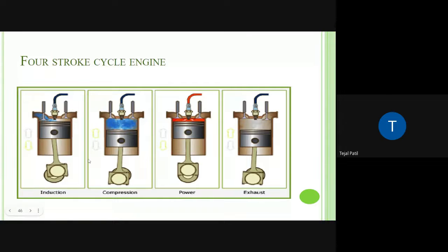So when it splashes, automatically that lubrication will be provided, that oil will be supplied to this moving part. Everywhere it will do splashing. That means the whole time the engine is going to be wet. That's why it is known as wet sump lubrication.